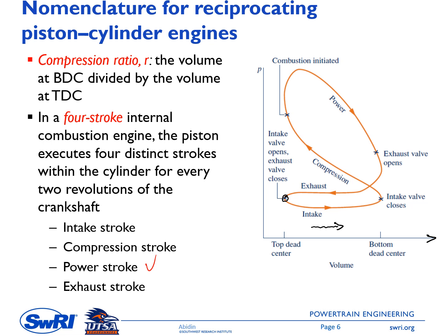Okay, and then the engine is conducting an intake stroke and the piston moves down from top dead center until it hits the bottom dead center at this point. So I can put here point number 1, here point number 2. Okay, and then at this point, for the ideal process, the intake valve closes and then the piston moves up again towards the top center, following this process line.